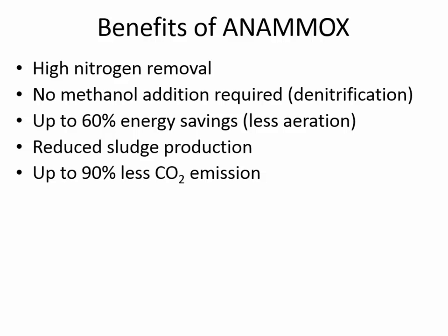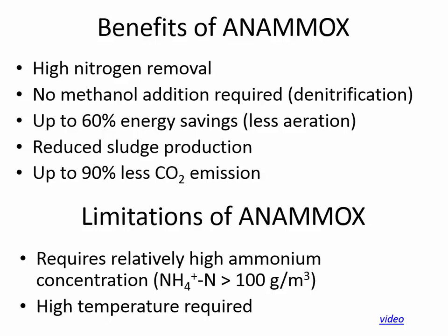We have to de-water it, and then landfill it somewhere or burn it. Whatever we have to do with it, it's expensive to get rid of. So reduced sludge production is a nice benefit. The other amazing thing is that it generates less carbon dioxide. There are some greenhouse gas implications of some of the steps in wastewater treatment, and ANAMMOX has benefits there.